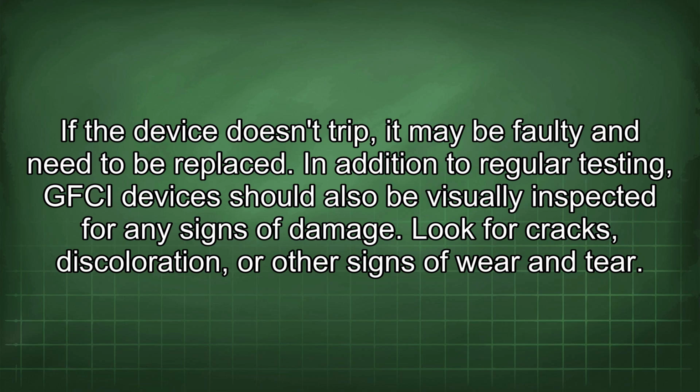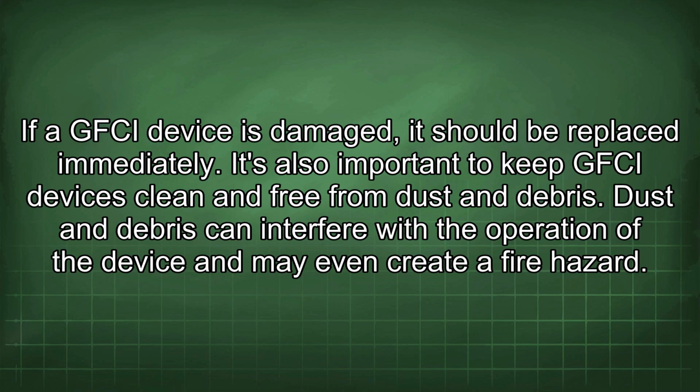In addition to regular testing, GFCI devices should also be visually inspected for any signs of damage. Look for cracks, discoloration, or other signs of wear and tear. If a GFCI device is damaged, it should be replaced immediately.